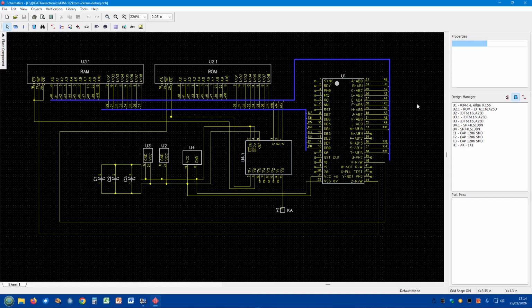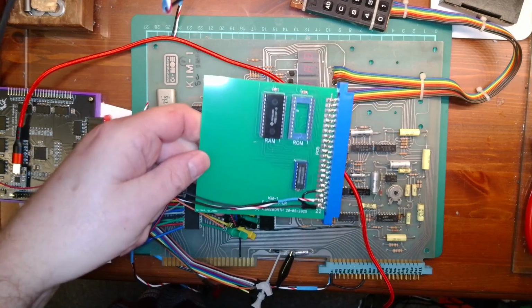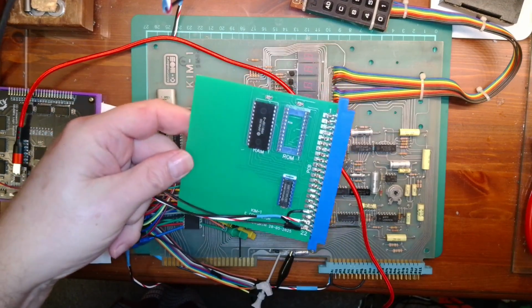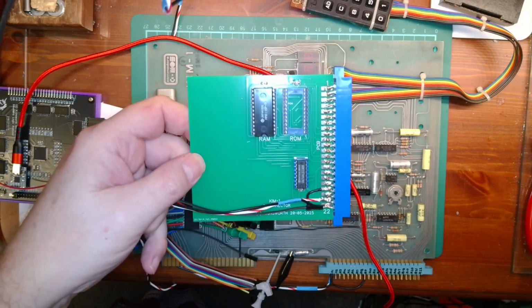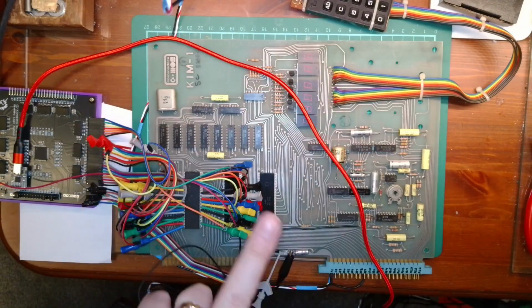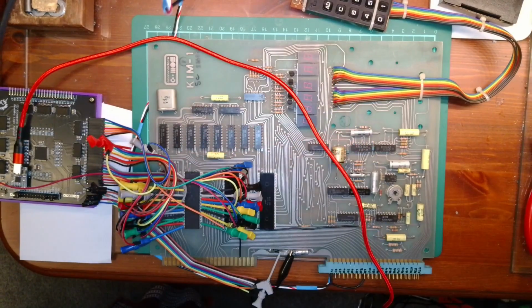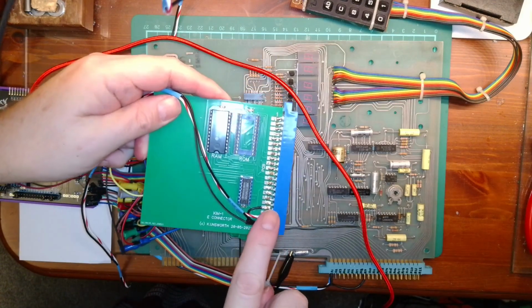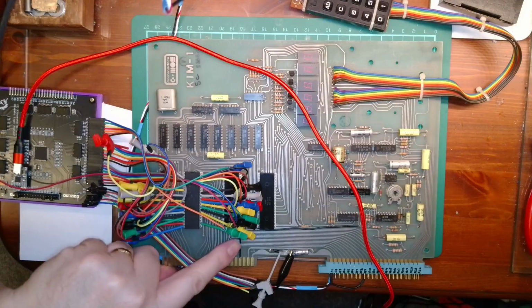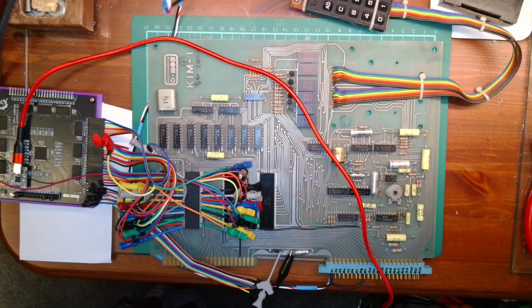So if we look at the actual board, we switch cameras. The actual board is this board here. RAM and ROM. The ROM's missing at the moment. That'll be plugged in there, and when that's plugged in, the idea is the KIM will boot off of this board and not this one here. Thus we can run our own diagnostics code on this to see what's happening about that D0 and D1. You see I'll put a link in here that jumps across that spare way, which jumps onto this wire link going across here, which is for the onboard decoder IC.